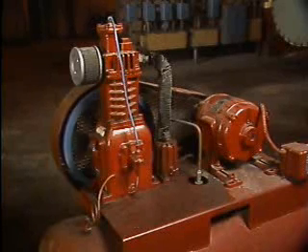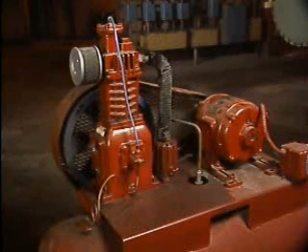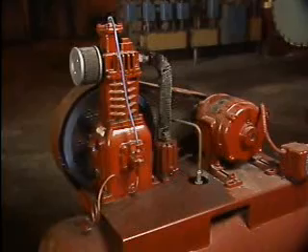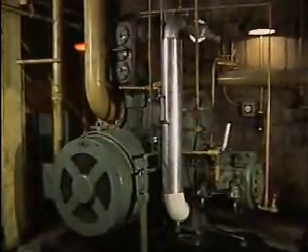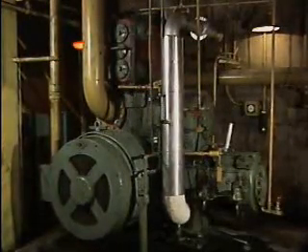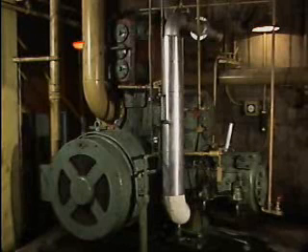When the pressure in the receiver increases to a preset value, a signal is sent to stop the compressor. When the pressure in the receiver drops to another preset value, a signal is sent to restart the compressor. Large compressors tend to be more efficient if they operate continually. So one device that is commonly used to prevent overpressurizing the receiver is an inlet valve unloader.